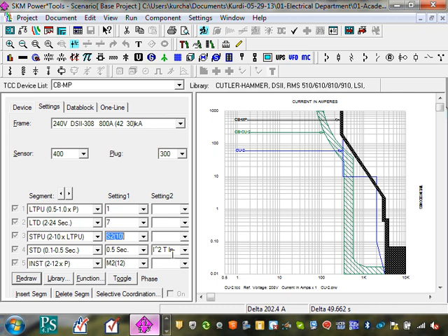Short time delay, I want that 3000 amp short circuit to sit on my system, look at that, for 0.5 seconds. It's an eternity in terms of arc flash. I can change this one. Right here, you can adjust that one too. That's so I can go 0.4 to 0.1 of a second. Can you guys see how it adjusts the curves? The curves keep going.